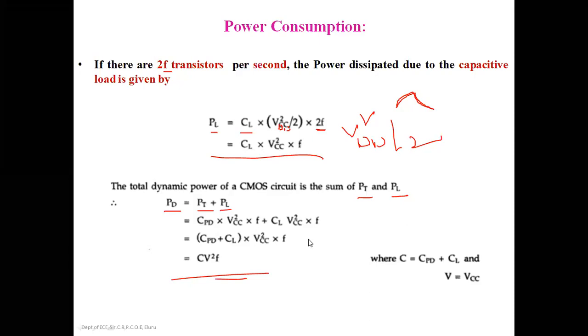And the dynamic characteristics are only 2. One is the speed of the CMOS device and the second is the power consumption. The speed depends on two characteristics, transition time and propagation delay. The transition time depends on two times, rise time and fall time, TR and TF, whereas the propagation delay is determined by two timing intervals, TPHL and TPLH, the propagation delay to change the state from high to low and vice versa, low to high.